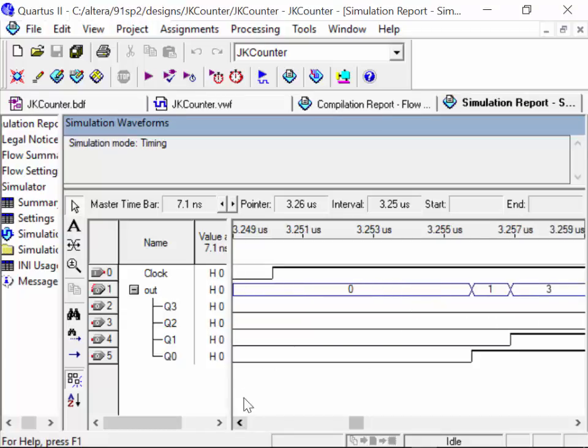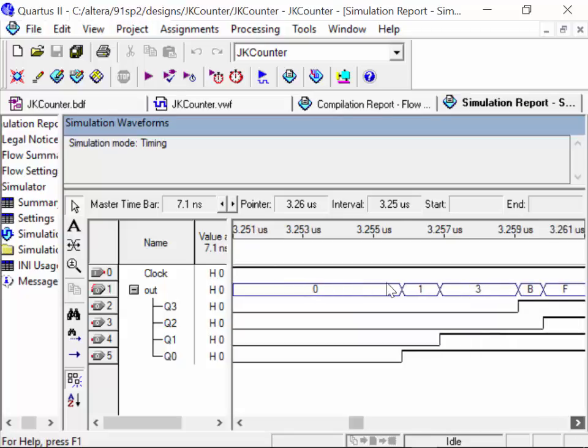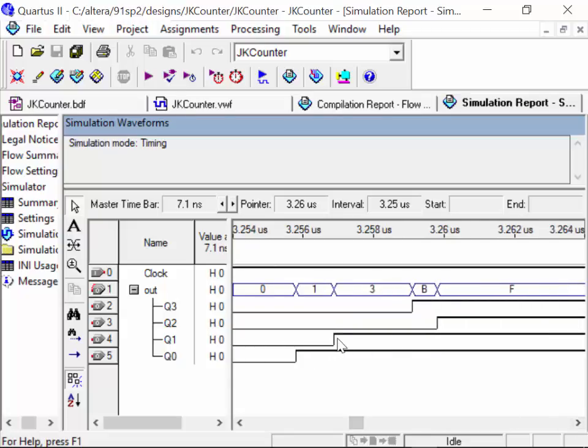Where's my clock edge? You see, there's where my clock changes. It takes all the way to this time here before the first one changes. And then after the first one changes, this one changes. Then this one's supposed to change, then that one changes. We've got some kind of conditions going on that causes the race.